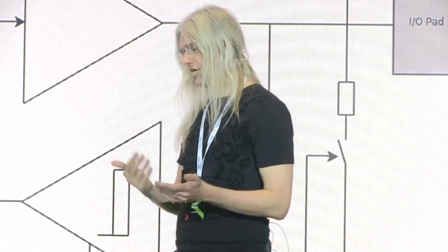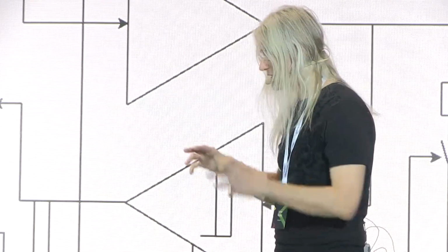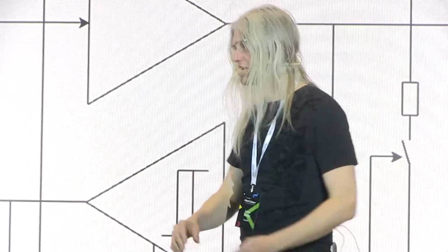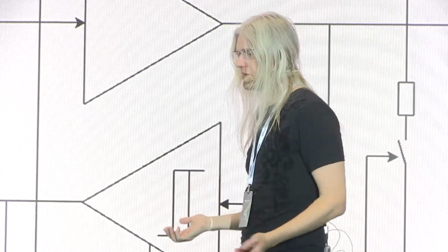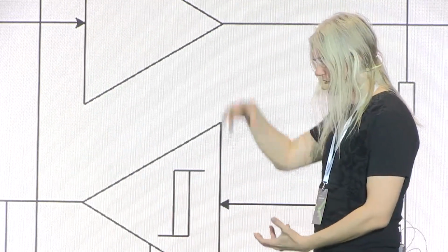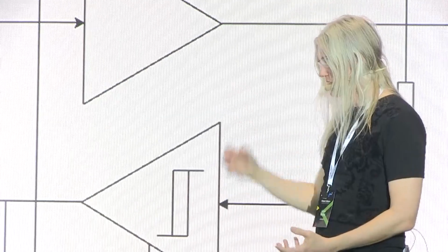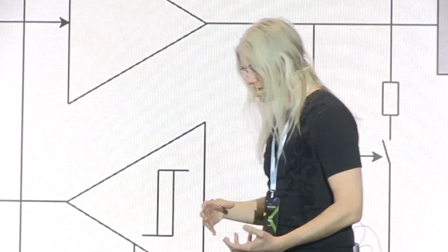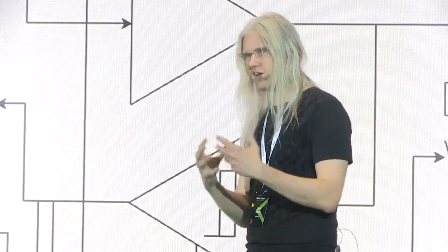And those libraries can contain a lot of things: gates, counters, entire blocks of buses, like an SPI block or something like that, that they just jam into their design and build their chip around. It's a hierarchical thing. It goes from the lower to the higher, and at the bottom of it is usually these cell libraries.